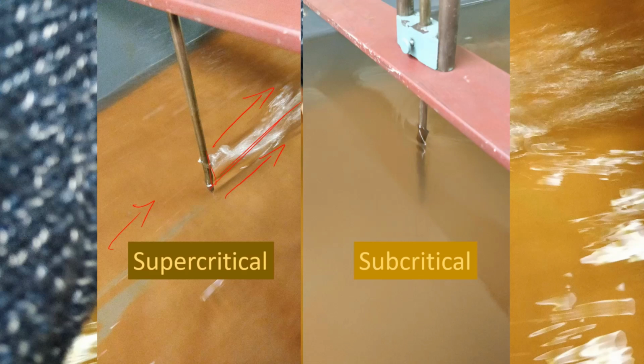In subcritical flow, we get little waves coming back up. They're also going downstream. So subcritical flow affects both upstream and downstream, and that's an important thing to realise. You've seen this in this lab already. When we've raised the weir, it's actually increased the depth further upstream. So subcritical flow affects both upstream and downstream. Supercritical flow only affects downstream.